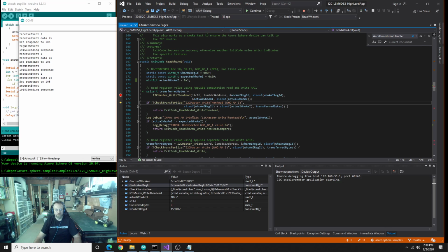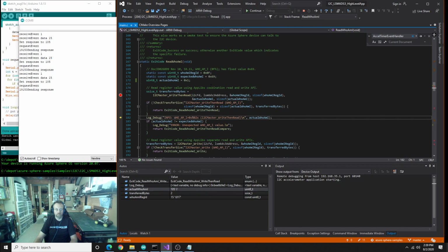And you can see that we managed to actually wait the 3 seconds needed. And so we transferred 2 bytes. And the actual who am I, instead of being a 1, is the 105 that we're expecting, the same as expected. And so now we can continue.